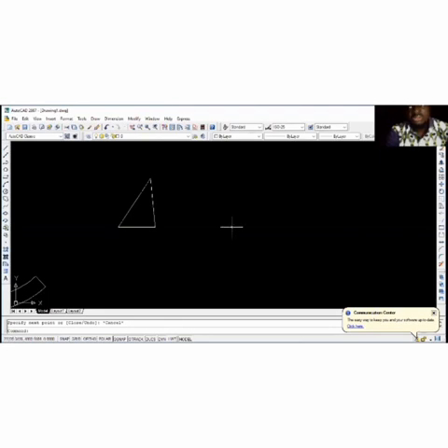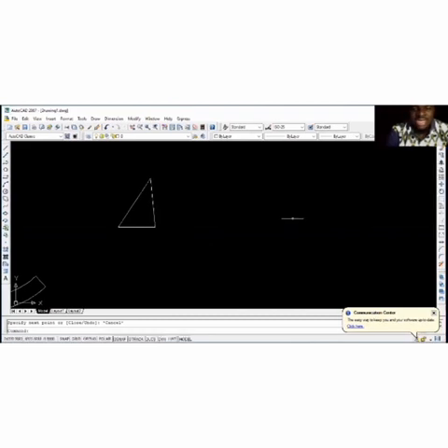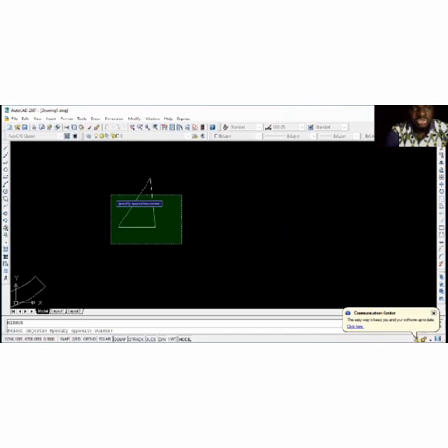What you just need to do is come to your mirror command under the modify toolbar, or you can just type the alias MI, enter. You just bring out your command. Now on the command window, you can see you already have mirror, and it says select the object. So now this is the object you want to mirror. So you can use your cross window selection.